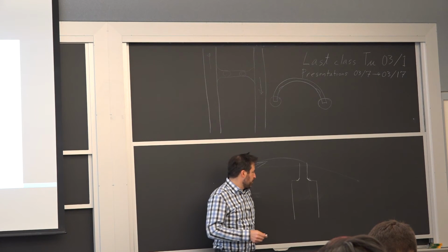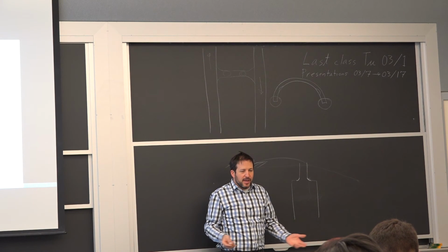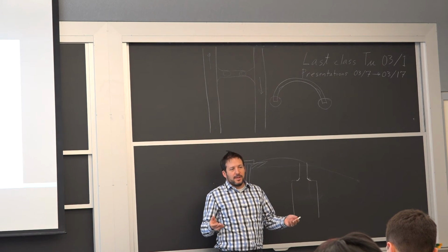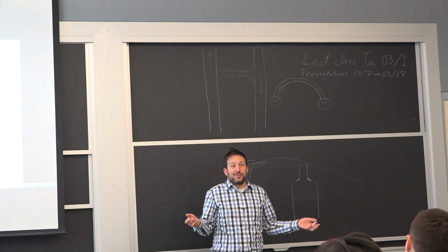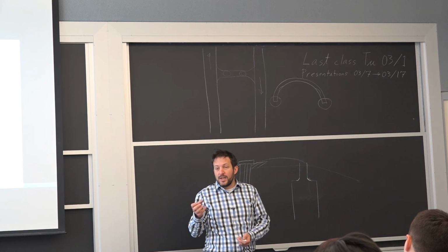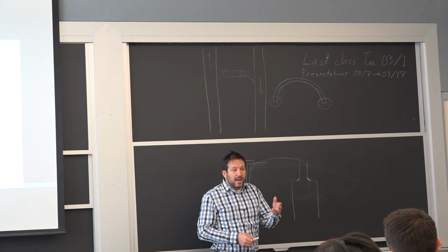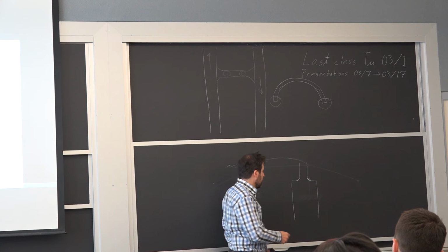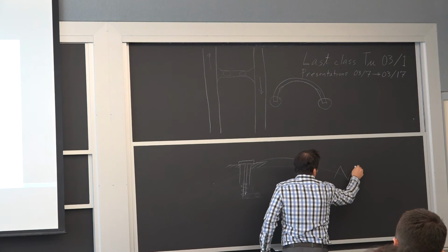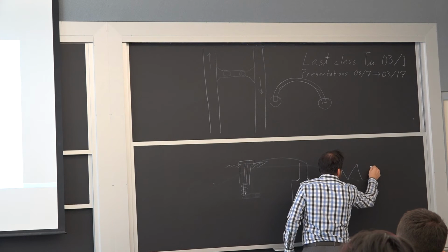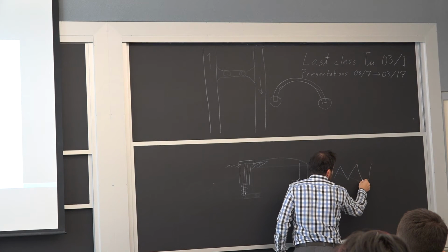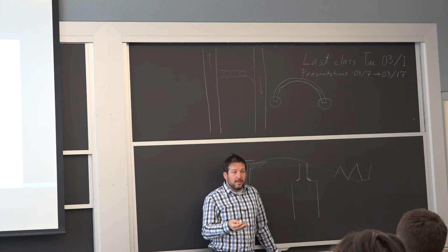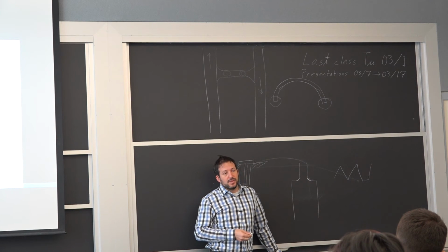So in that sense, exactly your radius, your minimum radius and the tolerance of it in this area is extremely important. If you have a relatively big part, like I think I showed the example of a fitting, the outside surface of the fitting in general just doesn't matter at all. What is going on at the root of a thread for that fitting is really where the stresses are. With a threaded connection, if there is any reentrant corner, if it's machined sharp like this, or if forging caused a little bit of a notch here, which happens, then that's where your cyclic resistance is going down.